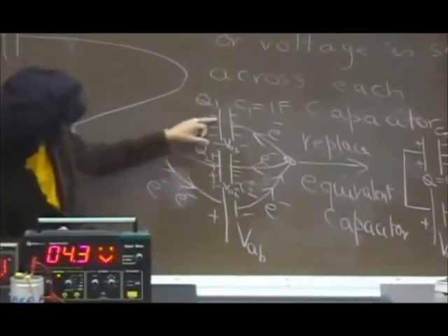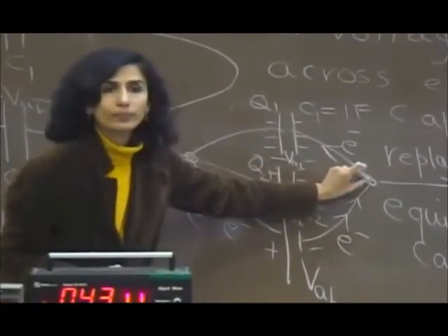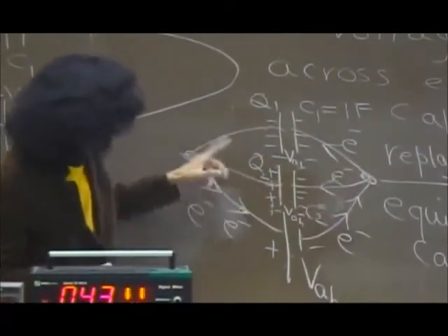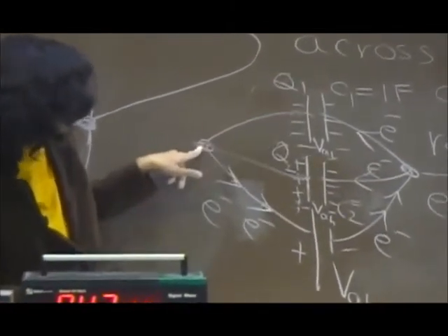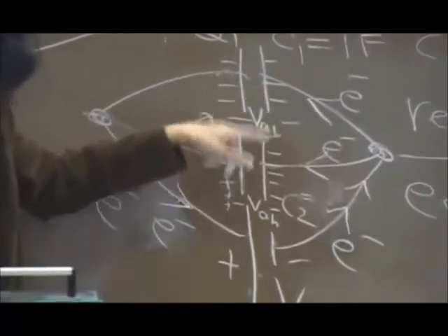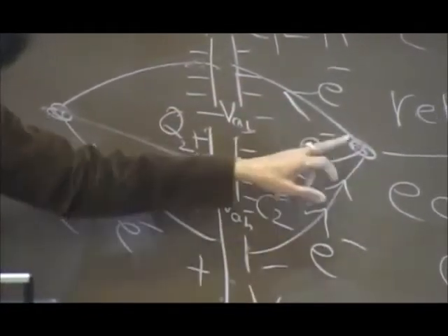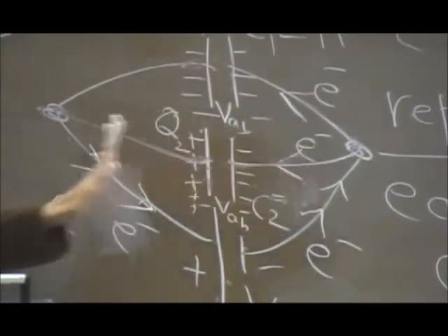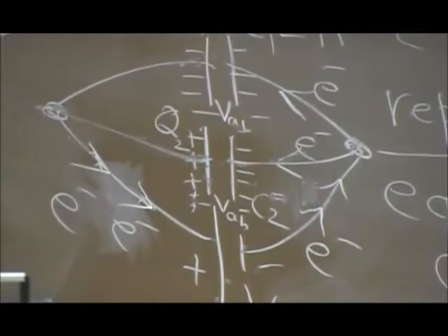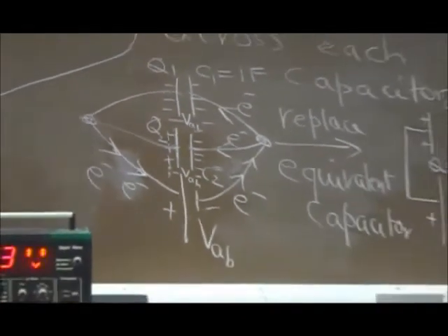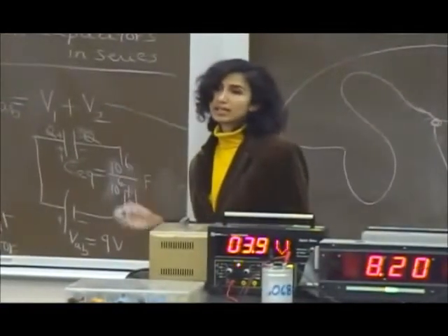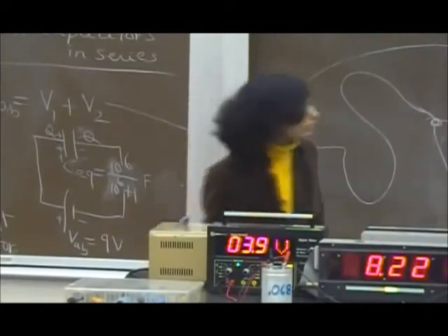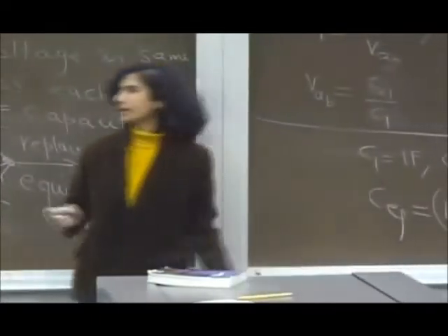So both of these capacitors should be meeting at the end at 2 junctions, and there shouldn't be anything else in between. So look, this one is joined at this junction, this one is joined at this junction, this capacitor is joined at the other end with this junction, and here at the other junction. There's nothing else in between here. That's why these things are in parallel. Is that making sense? Okay, now what about those cases where the capacitors are partly in series and partly in parallel? So let's try to do those cases. So capacitors partly in series and partly in parallel.